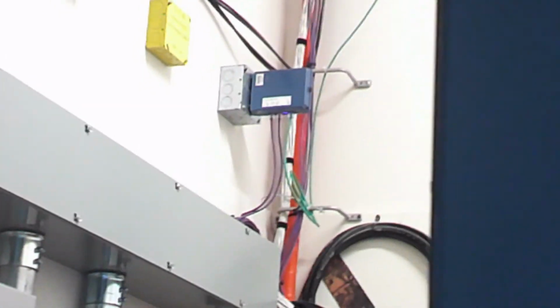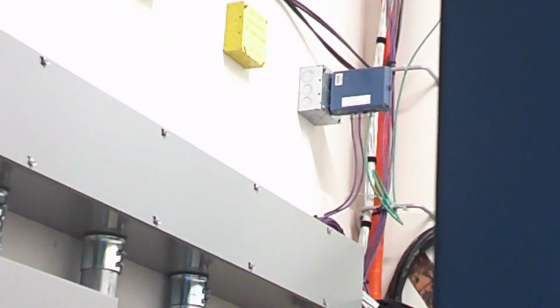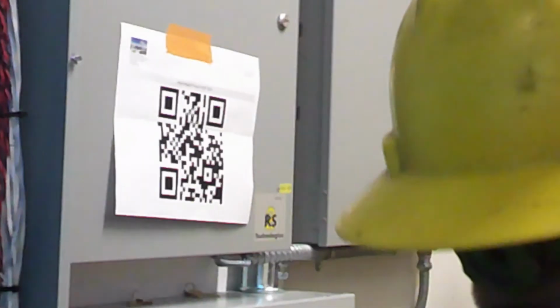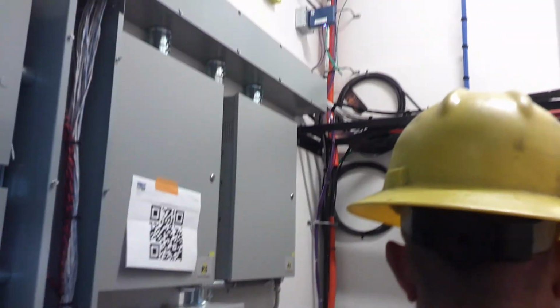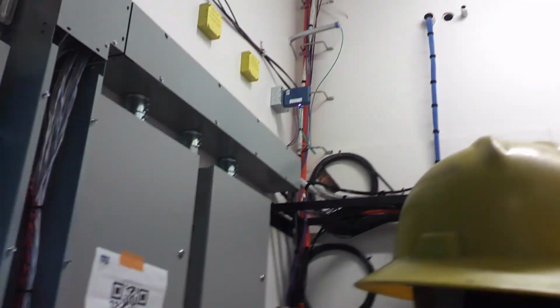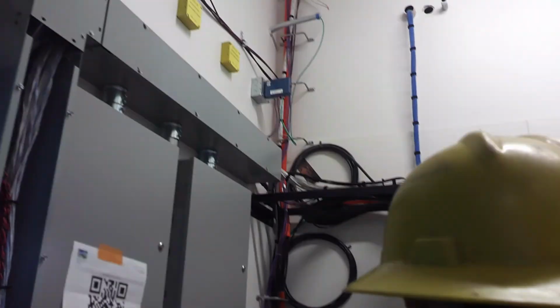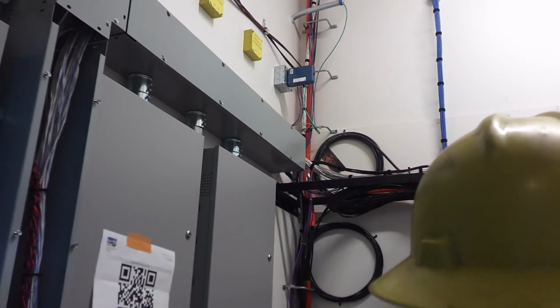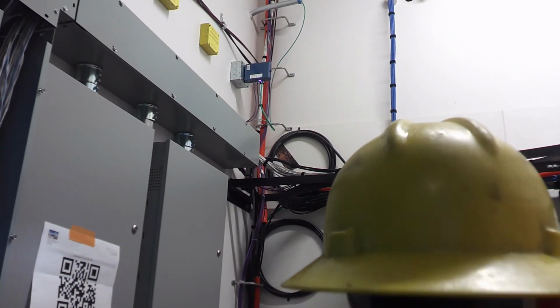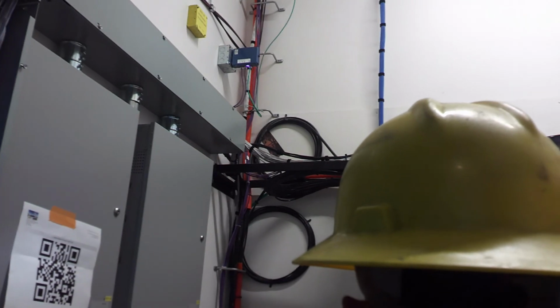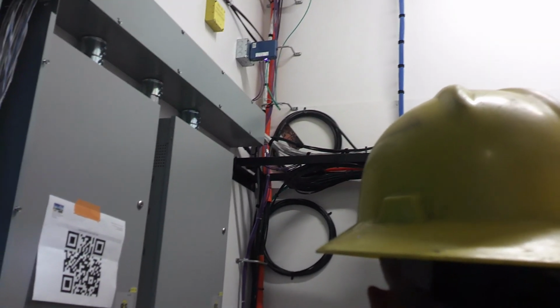Which does this go on? That's upstairs somewhere? I think it's just in the electrical room, just right across here. So what is the PoE power? The bridges, they get power from the room controller typically to operate. Okay. But say you turn off a circuit and that room controller loses power, that bridge will grab power from the 2 bridges before it. So this thing does put out power on those cables, but it's not really its biggest purpose.